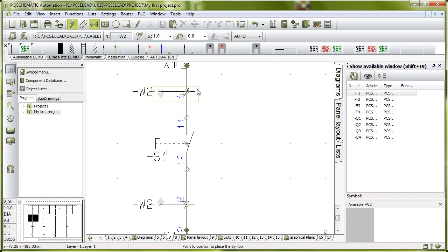They are correct, meaning that my wire comes from this terminal in this direction to this external component, and from this connection here, it has that direction to this external component here. And on this page, the direction arrows make perfect sense. And you can see what it means in the lists here. I can see I have a terminal, I have a cable list.